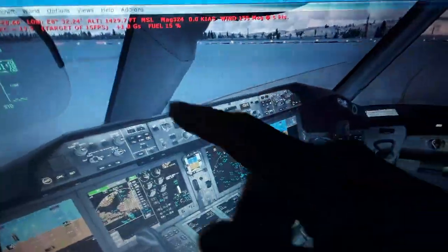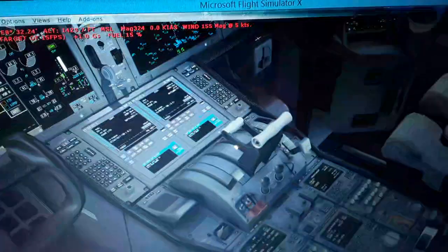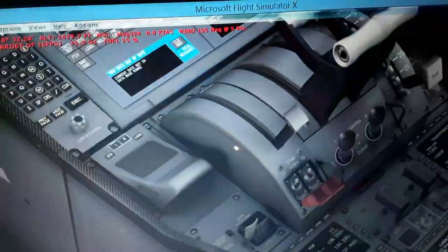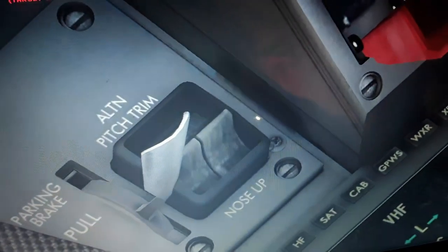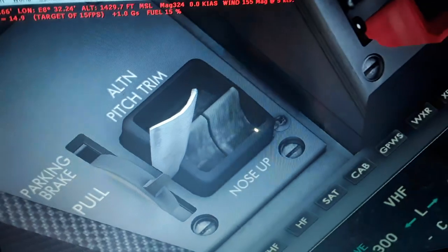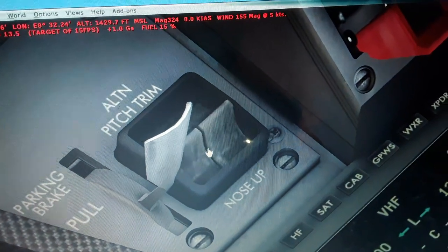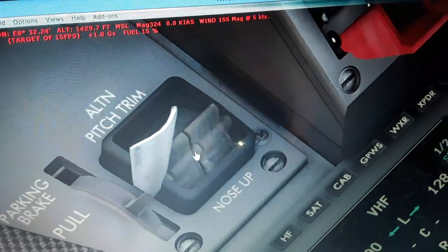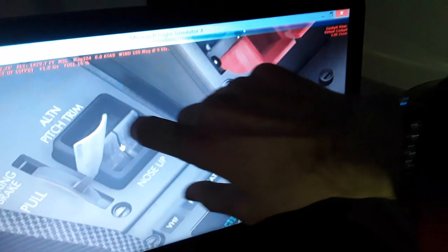Maybe for both, if you disconnect both, you will have no autopilot. You have to fly manually. Also, you have to use the manual trim switch for the horizontal tail over here. So you use the manual anyway when you fly manually. You can see this way you trim the elevator up. You pitch the nose of the aircraft up as you fly.